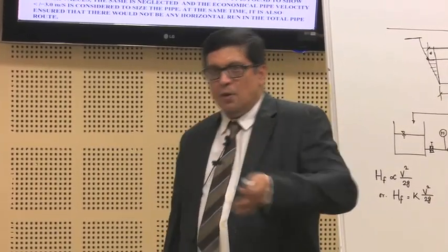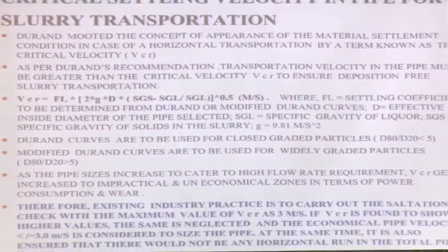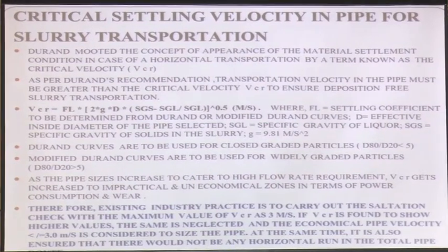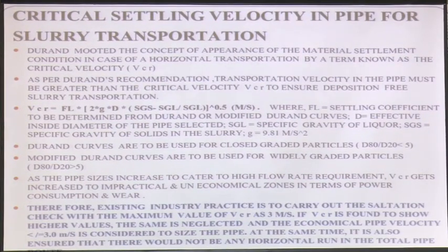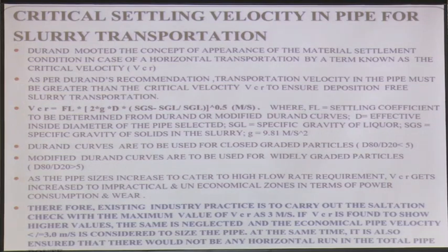The more you go up on the pipe diameter, this becomes unrealistic. What is that nomenclature, 200 NB? NB is the nominal bore. As per the IS standard, Indian standard, there are 2 standards: IS 1239 part 1, which covers up to 150 NB, and IS 3589 that covers beyond 150 up to 500 NB.